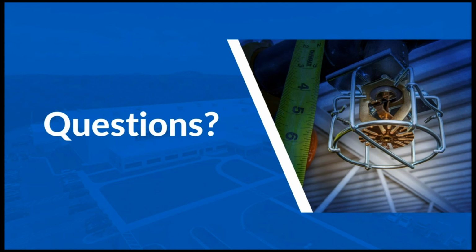Going back to the combustible concealed space sprinklers and rising up to an upper level. The question is, does a single CPVC riser feeding a sidewall sprinkler on an upper level have to follow one of those protection options? Yeah, this is not about the number of risers. It's about a riser that doesn't meet one of those 3 options.